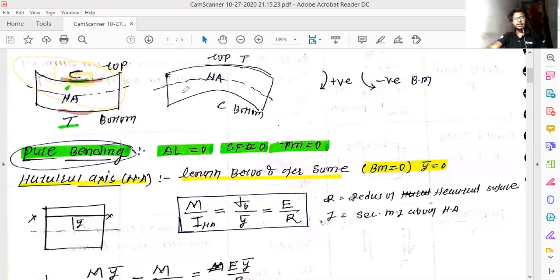And similarly for the hogging moment, which is just to the right of that diagram, as we've seen. We take a clockwise moment as positive, and an anticlockwise moment as negative. It's totally based on your choice, but keep in mind that you have to follow the same notation throughout the entire section, because otherwise it will create some confusion while solving this kind of example.